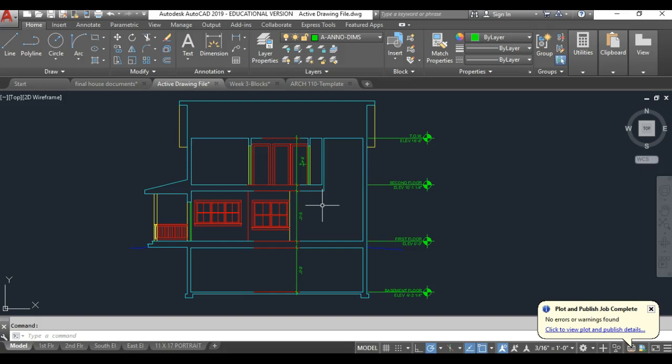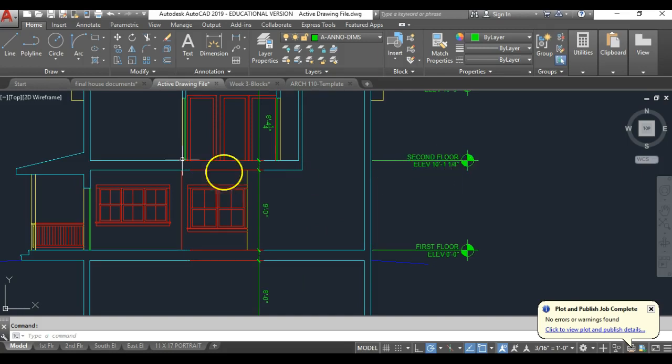And so how I would typically get that is if I knew the floor to floor height, which in this case we have because we've drawn the section, and oftentimes to get to this level of detail you have to already have a section drawn and you have to figure it out. Then you have to go and edit the floor plan to update that information, but in this case we've done it for you. But I'm going to draw a line from the floor plan down, and actually I didn't even need to draw that line. Really I just need to know a height that I can measure from the second floor plan to the first floor plan. But I see it here because I have an elevation 0 and an elevation 10, 1 1/4.